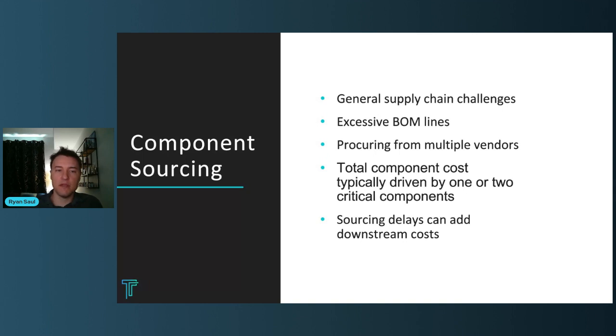And so before you even begin layout, understanding what the material cost of your BOM is going to look like and be characterized by is really important, particularly when you get to mass production, because your build can only get as inexpensive as your materials. In many cases, individual component choices are going to provide the long pole in the tent on your assembly when you get to mass production. So if you've got a $5 microcontroller on your board, that could be a $2 microcontroller. During prototyping, that's not a huge difference, but during mass production, that might be an incredibly material cost difference.